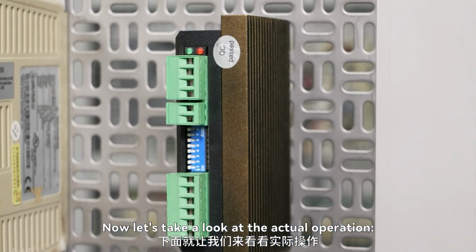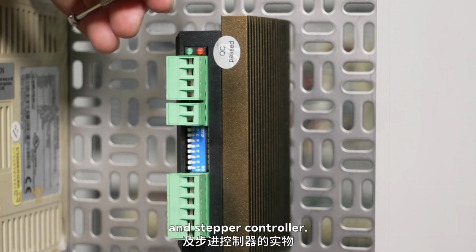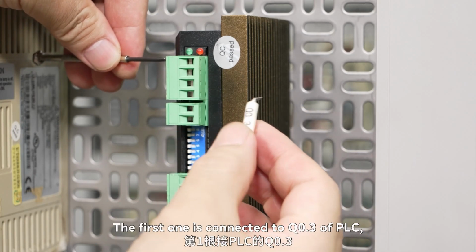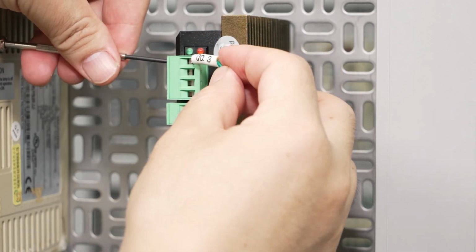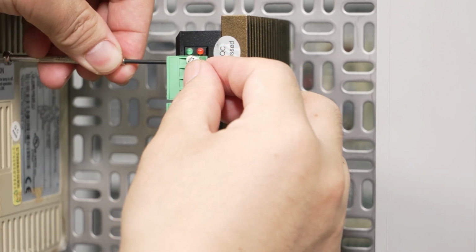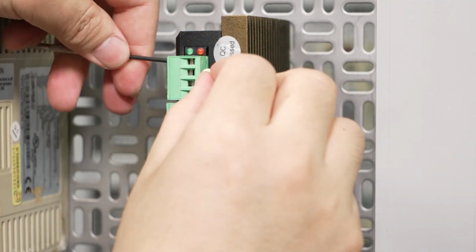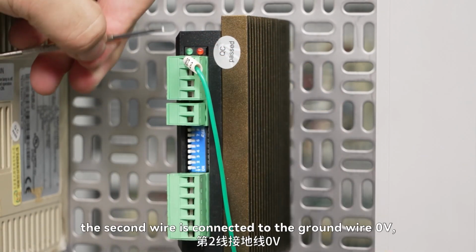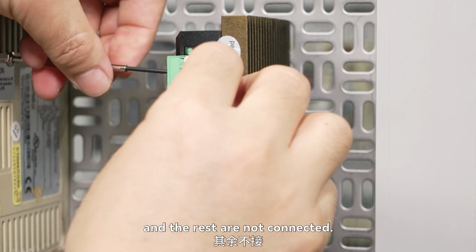Now let's take a look at the actual operation. This is the physical stepper motor and stepper controller. Physical wiring of the step controller, 2 P1 wires. The first one is connected to Q0.3 of the PLC. The second wire is connected to the ground wire 0V, and the rest are not connected.